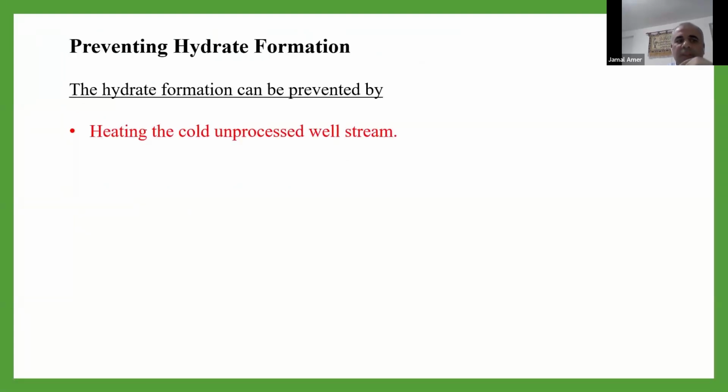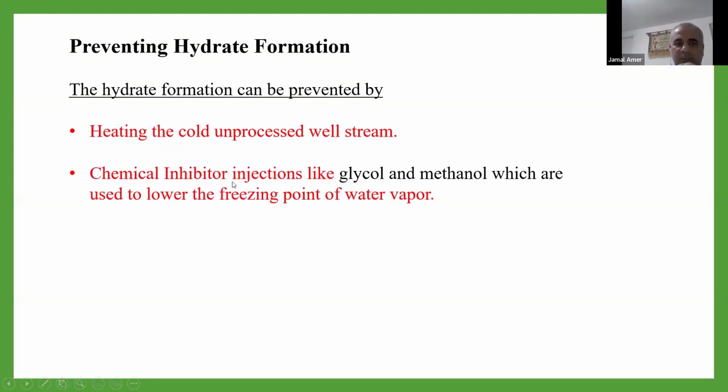How can we prevent it? Hydrate formation can be prevented by heating the cold processed gas stream, or by chemical inhibitor injection like glycol or methanol.